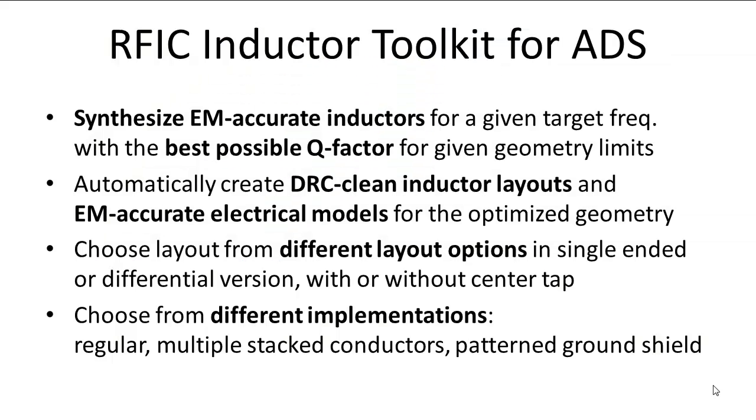So, RFIC Inductor Toolkit for ADS does the work for you. You just need your specifications, and Inductor Toolkit will design that inductor for you. It synthesizes EM-accurate inductors for a given target frequency with the best possible Q factor for the given geometry limitations. It also automatically creates EM electrical models for the optimized geometry, so you get the proper SPICE equivalent circuit models.